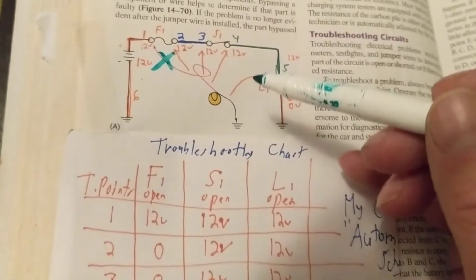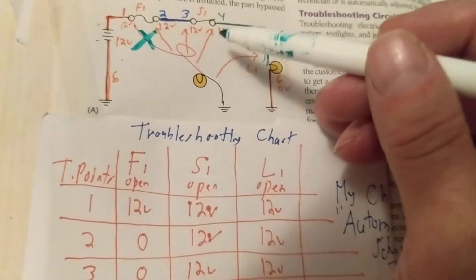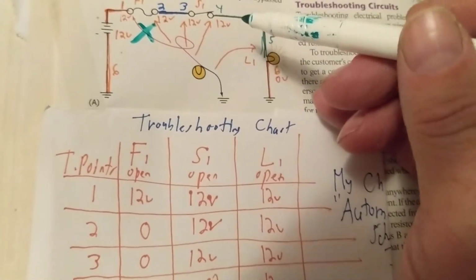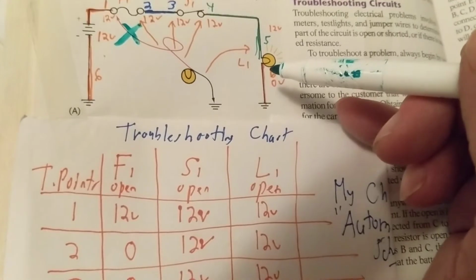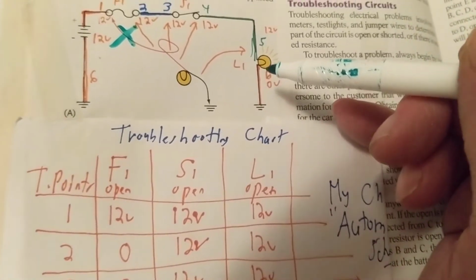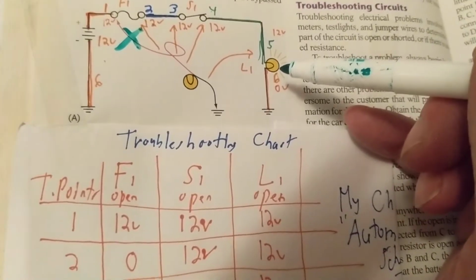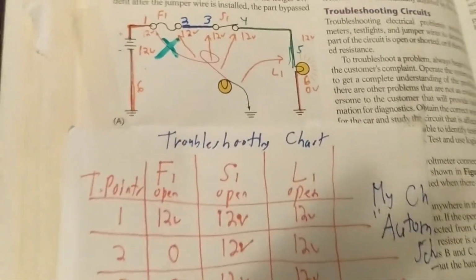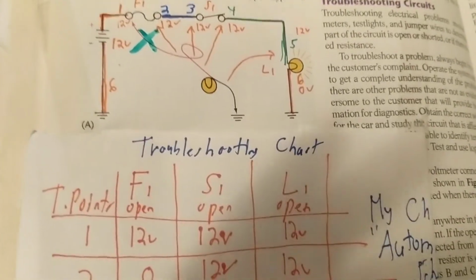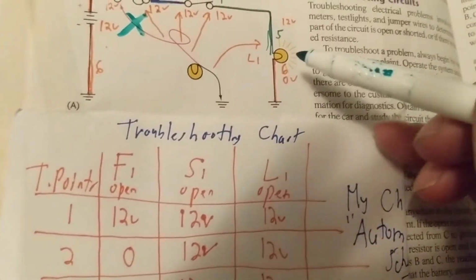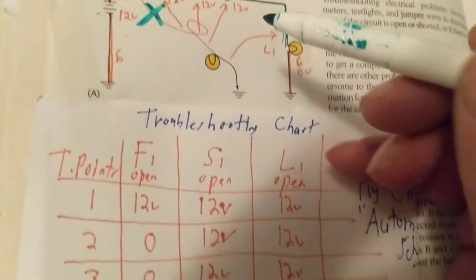Let's take another faulty component in automotive. S1 has a problem. Right? I close the switch in the car to try to illuminate the light inside, the cargo light, anything, the glove compartment light. It doesn't go on, right? I look at the light, I close the switch, I say, okay, where's the cargo light? Where's the dome light? It's not lighting. Okay, is it the switch? Is it the bulb? Is it the fuse?